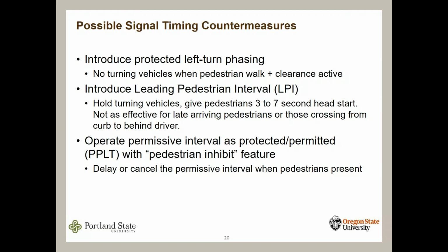Another option is the leading pedestrian interval, where the pedestrians get a head start 3 to 7 seconds to get out into the crosswalk. And I think if you spend some time and you go back and look at some of the data that we reduced, you'll notice that when there are more pedestrians, the drivers are sort of more likely to search and sort of notice the pedestrians.